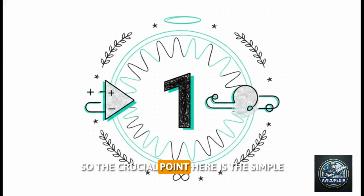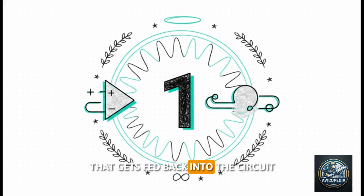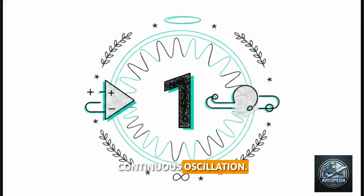So the crucial point here is this simple but massive equation: MV times AV equals exactly 1. AV is the voltage gain of the amplifier, and MV is the fraction of that voltage that gets fed back into the circuit. When the product of those 2 numbers equals precisely 1, boom! You've achieved the holy grail of perfectly sustained continuous oscillation.